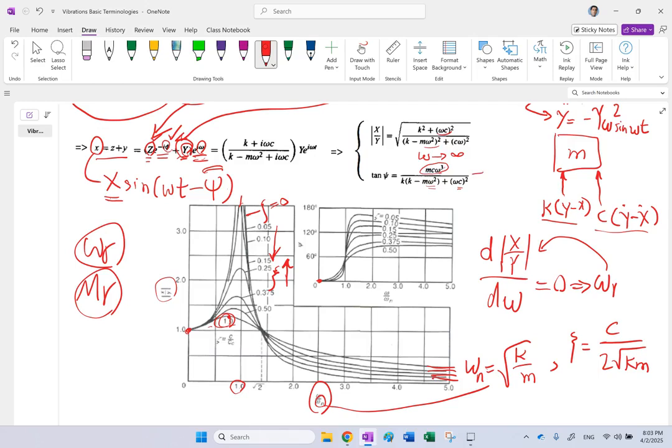So the whole thing will go to infinity when omega goes to infinity. So tangent of psi is infinity, so psi should go to pi over 2, as opposed to the other plot where they all converge to 180. In this case, you see as the angle gets bigger and bigger, they are all converging to 90 degrees. So you see they're all coming down and converging to 90 degrees when omega becomes very large.